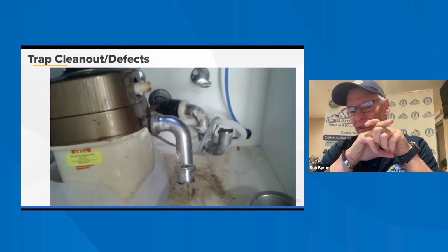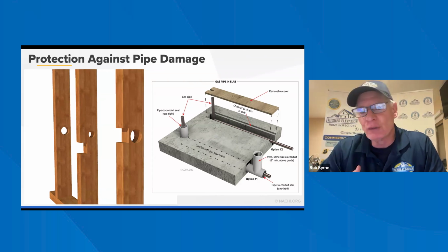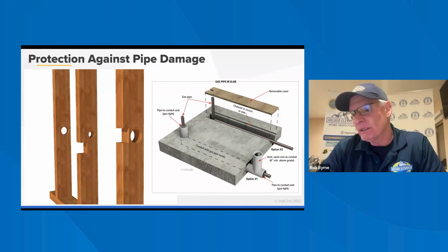Shielded plates, fuel gas piping. For gas lines, the plate should extend a minimum of 4 inches above sole plates and to both sides of the studs or rafters to prevent puncture risks. So basically, if it's too close to the stud, or there's a possibility of putting a long screw in, you don't want to hit any of that. So those are the pipe protectors for that. And again, you're not going to see this unless you're doing a pre-drywall inspection.